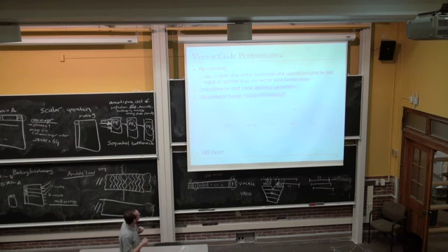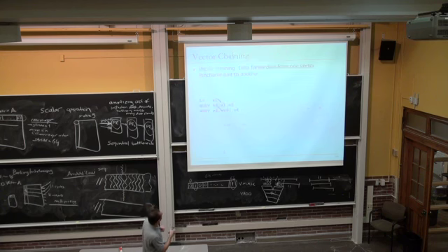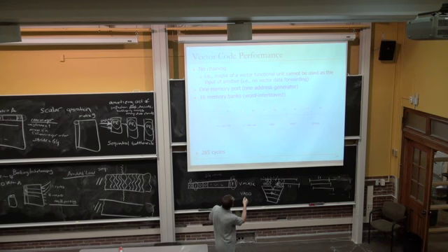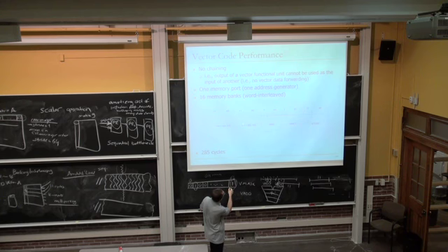Okay? But now we're going to do something like what you suggest. Basically, there's no reason to start this add here. You can start this add right here, right? Because you have both of the first elements of the vectors available at this time. And there's no reason to start the shift until you've finished all of the elements. You can start the shift of the first element right here, right?